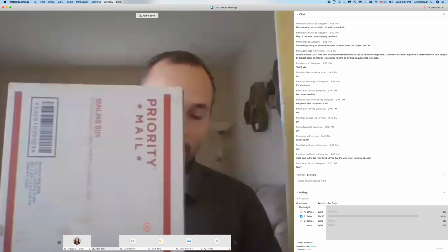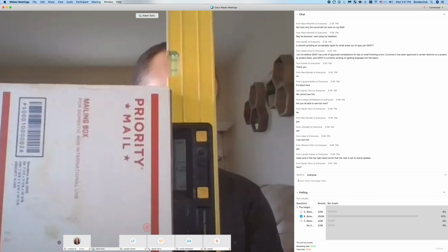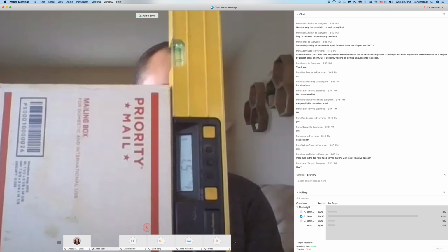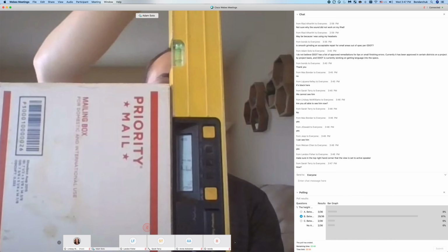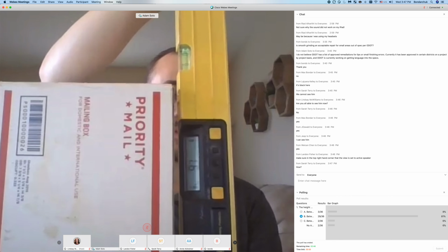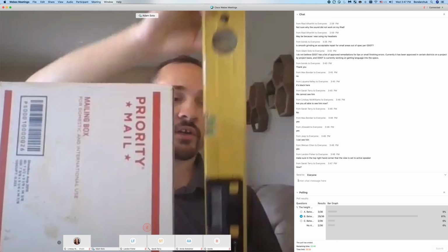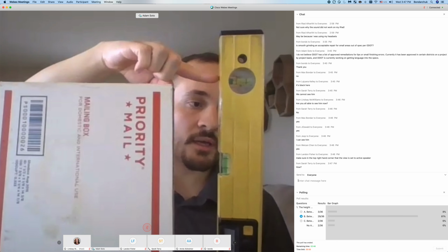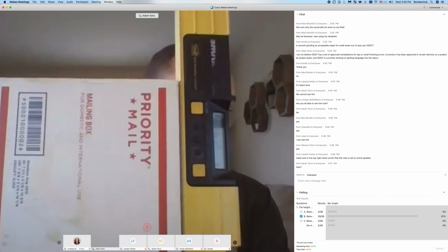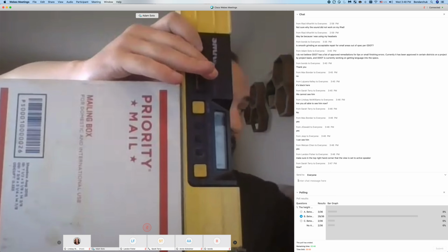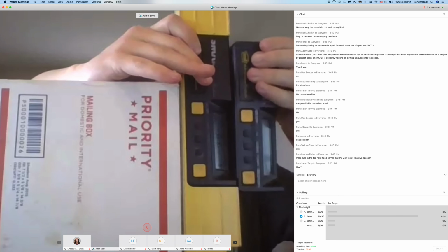So the next part, we're going to go to a wall and use a wall for the vertical calibration. Again, I'm going to use this box for ease of viewing, but we would never do this in the field. And for the first 2 measurements, we're going to start with the bubble on the bottom. And if you're using the 6-inch Smart Tool level, that's going to be the screen on the bottom. So it'll be like that.